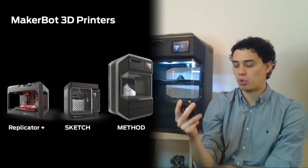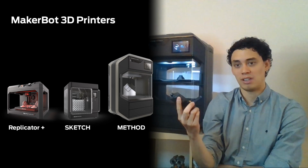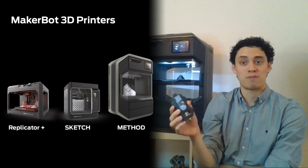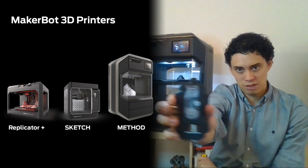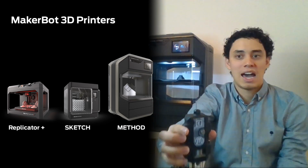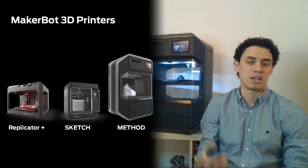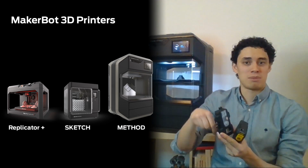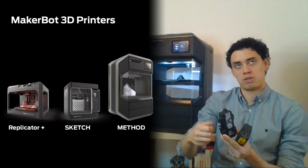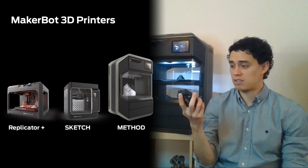But the thing with these extruders is that they are harder to jam because they have embedded sensors in them, right? So they will detect the jam before it happens and reverse this little extra tip of material, and make sure that they stop themselves before they create a more difficult clog to clean. So it's usually a matter of just purging the material, pulling it back out, and that's about it. So this guy is $250.